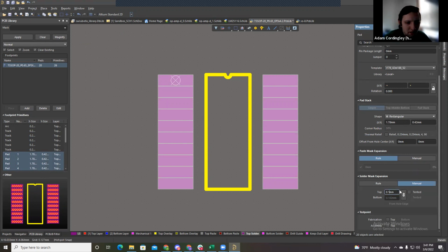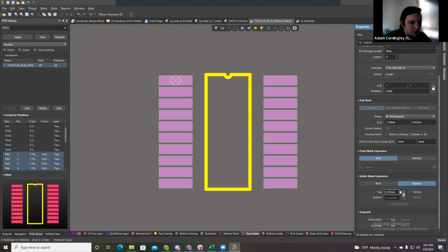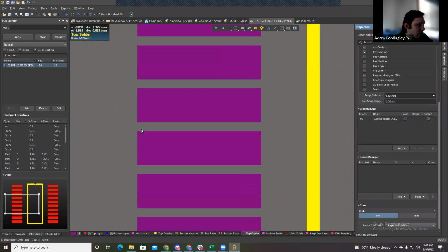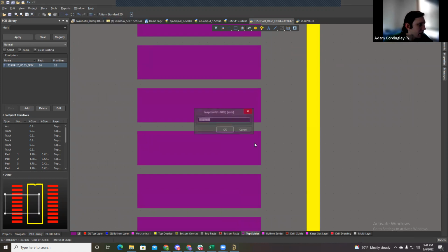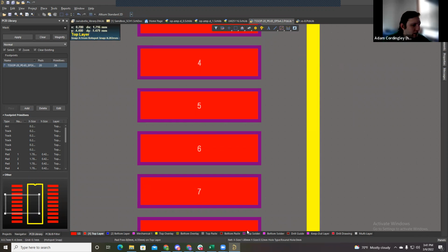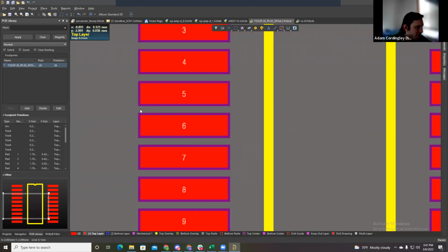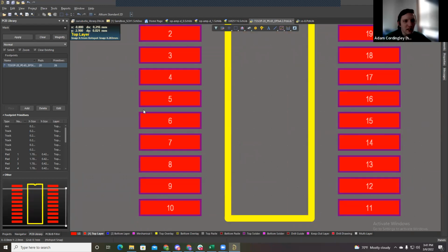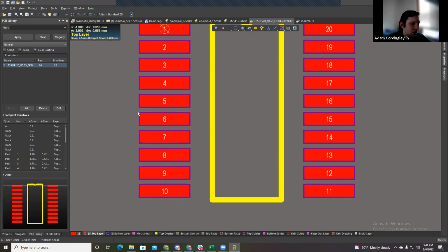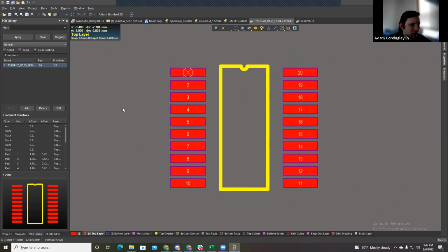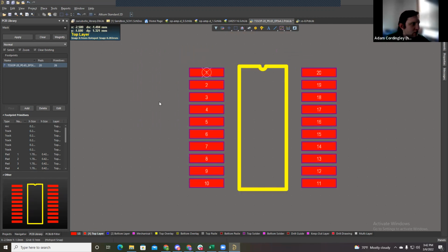You can usually cut this down to like 0.05 millimeters. And then you get a nicer, how much is that actually? So that's still probably not manufacturable. You know, like they'll still probably chop that away. Because if you look, it's about 0.15. Now, if you get green solder mask, they usually can make it slivers of like 0.1 millimeters. But other colors of solder mask tend to not have a smaller feature size. So your mileage may vary, but this is a good start.